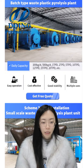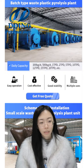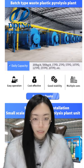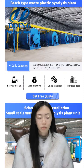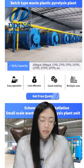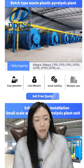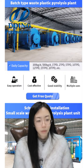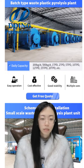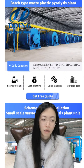With the batch type, we can get one batch per day. First we need nearly 1 or 2 hours to feed the raw material inside the reactor. Then we close the feeding door and open the combustion system to heat for the pyrolysis reaction. For nearly 10, 11, or 12 hours, all the materials will be pyrolyzed into oil gas. And the oil gas will go into the condensation system to condense into fuel oil.